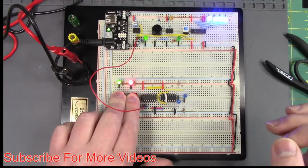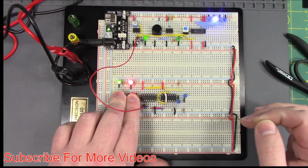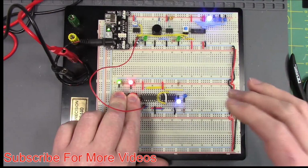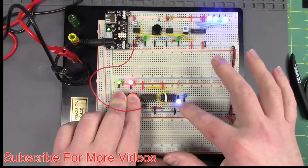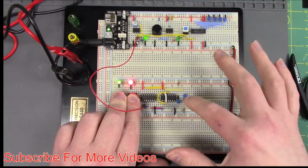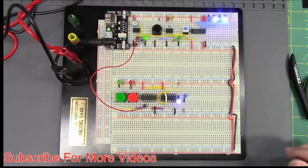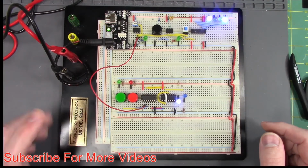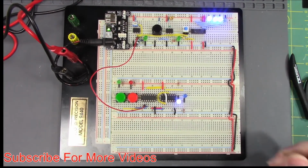But if you do use the master-slave function of a JK flip-flop, which I'm not going to be able to build in this video, you get rid of the randomness of it, and it would go back and forth evenly. So that is your JK flip-flop, I used a 74LS11 and a 74LS02.